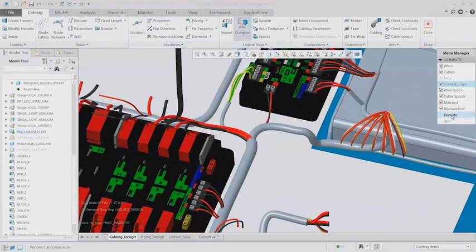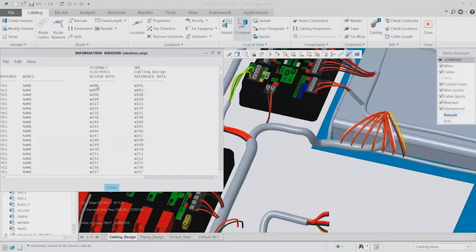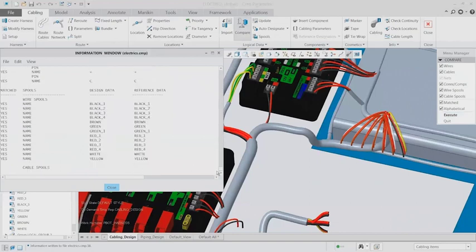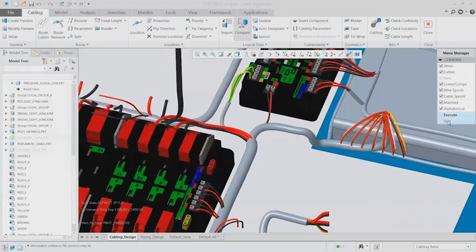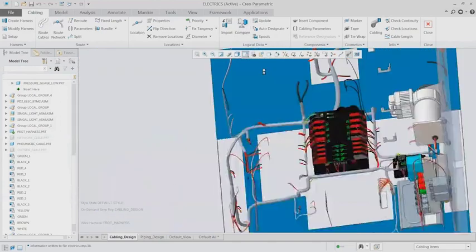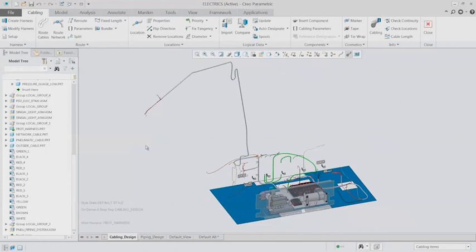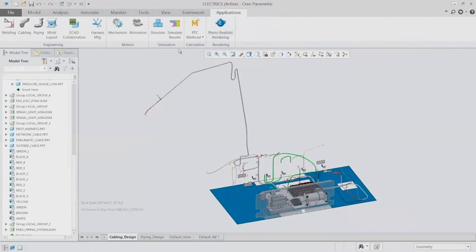So now at the end of the process, we go back to that checklist that we had, and this will allow me to check that work and make sure I have all the objects linked up against that overall Creo schematic. So this really allows me to not just build out a routed system within Creo a lot quicker than if we were doing the traditional method of creating 3D geometry for all these individual wires. It allows me to make sure that I always have the most up-to-date information from a schematic, and I might have all that logic defined ahead of time. So as a designer, I'm just doing my job in terms of going through and actually routing the cables, not determining where they're supposed to be going.